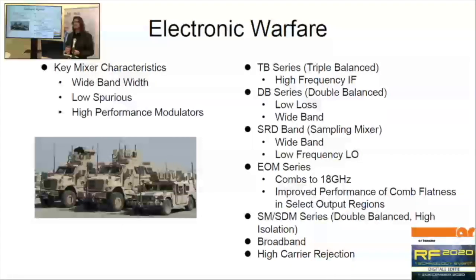But for sure, all of the mixers on the right might be available for that. I'm not going to mention them all, depending on what you want to do. But one thing at the bottom usually is high carrier rejection. That might determine already which kind of frequency or which kind of mixer you want to add to your list.